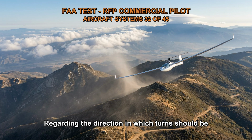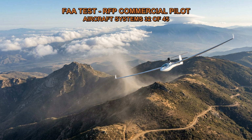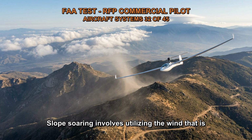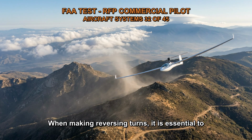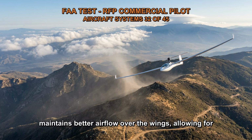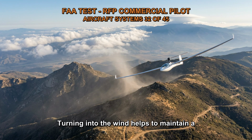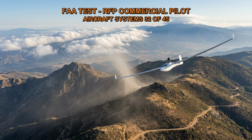Regarding the direction in which turns should be made during slope soaring, it is generally true that all reversing turns should be made into the wind, away from the slope. Slope soaring involves utilizing the wind that is deflected upward by a slope or ridge to gain lift and maintain flight. When making reversing turns, it is essential to maximize the lift provided by the slope. By making turns into the wind, the glider maintains better airflow over the wings, allowing for more lift and control. Turning into the wind helps to maintain a closer alignment with the slope, reducing the risk of losing lift and potentially encountering a loss of control.